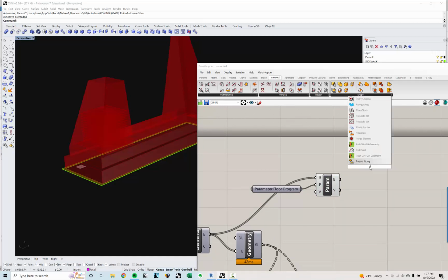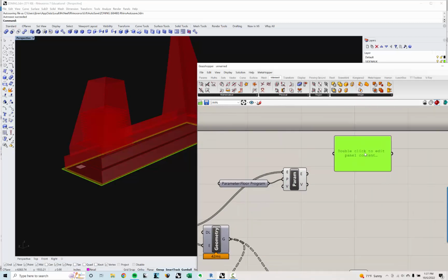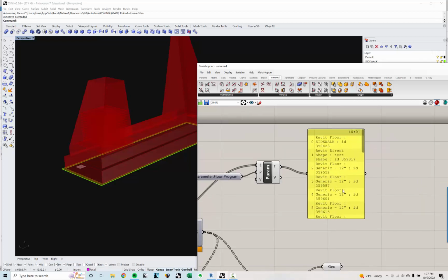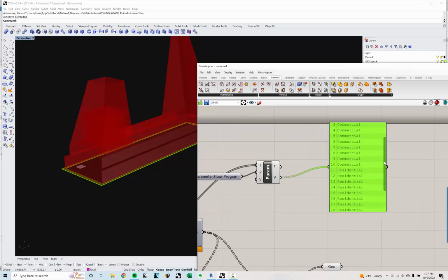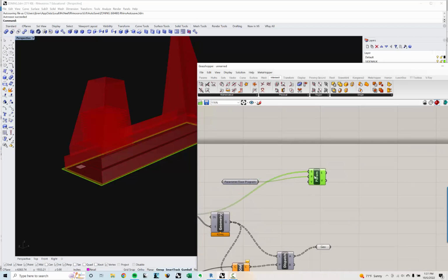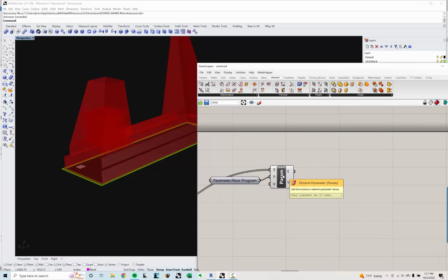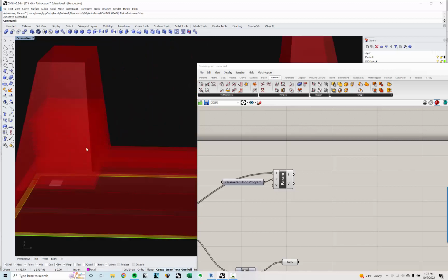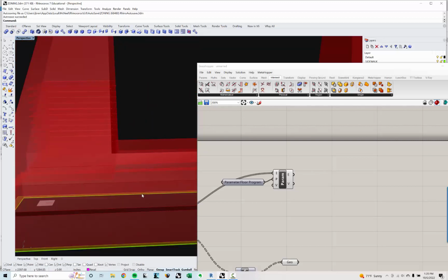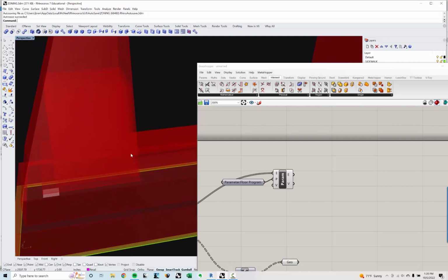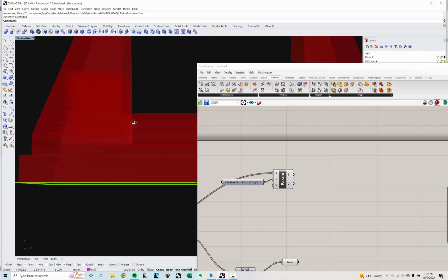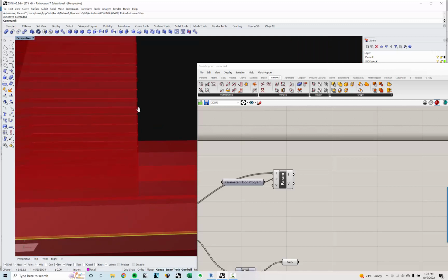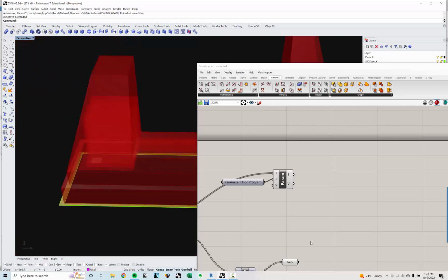And now I have essentially all the different elements coming through here and all of the different floor program components. So I have my nulls, my retail, my commercial, and my residential. I want to start to sort by, let's say, retail first. Why are these still not showing as compliant? Oh, they're sticking out the back a little bit. It's okay. You might want to go in and fix those because you would get rejected by the zoning review, but for the purposes of time, we'll just keep it going.